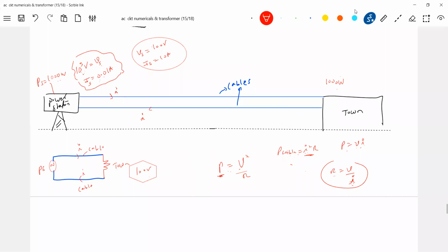So what is the requirement now? I need an instrument which can increase the voltage and which can decrease the voltage without consuming power. Sir, will we use a potential divider? No, a potential divider will consume power. So that is the reason why we are bringing in the transformer here.